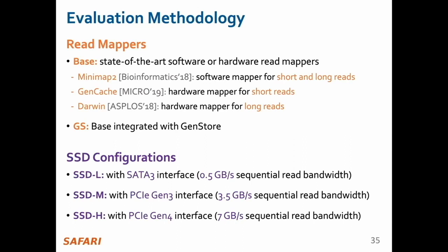For example, a GPU or an accelerator can be connected to those PCIe slots. So we have a smaller number of PCIe slots available for expanding the storage infrastructure compared to SATA, and it is also usually a lot more cost effective to use the SATA interface.